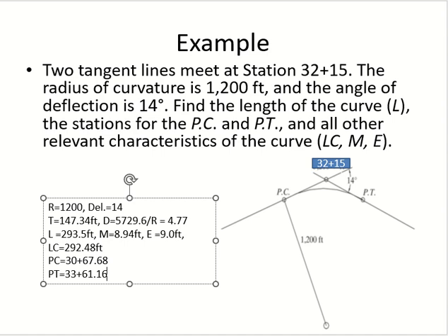When you do this plus tangent, you will get slightly ahead. It will be slightly more, so your curve will become longer. Get my point? When you do this plus tangent length, you will not get PC at this station. You will get it slightly ahead. So your curve will become longer by 1 or something feet. Clear? So this one is considered more accurate. Any questions?